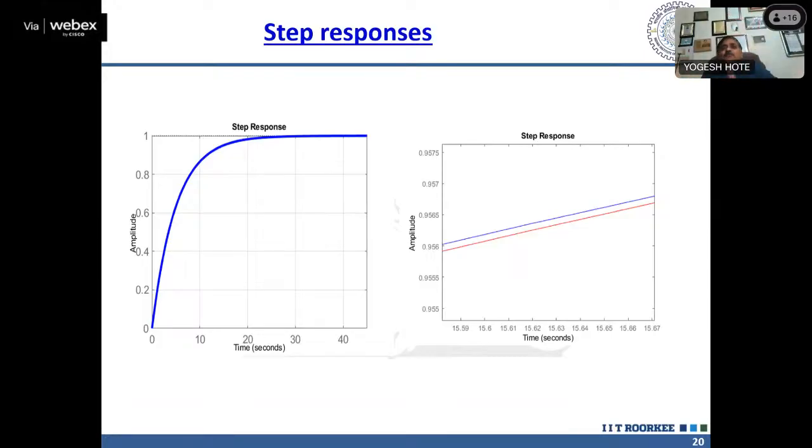So technically, in reduced order modeling, you have to discard the non-dominant pole, keeping the dominant pole, and the effect of the non-dominant pole should be merged. How to merge it? You determine the steady state of the original model, equate it to a factor K multiplied by the steady state of the reduced order model. From this you calculate K, and K is multiplied with the reduced order model. If you do this, the response will match. This is the fundamental concept of model order reduction.